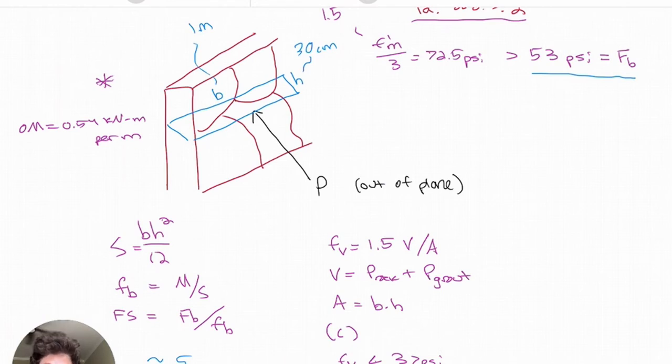So the conclusion here is there will be an obvious addition of capacity from the strength of the wall. However, there are many factors and unknowns throughout a build that can't truly be accounted for by a general check like this. How much wall is built before the fill, the embedment of the wall in the soil, the workmanship, the height of the walls, the time to cure before being filled, and much more.